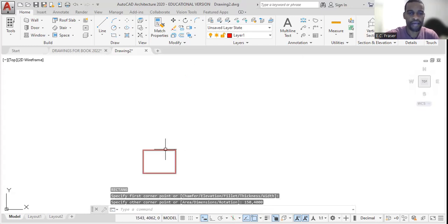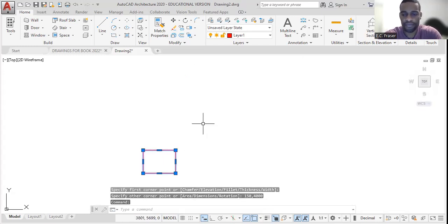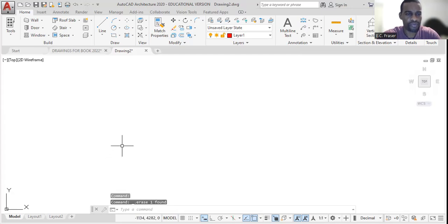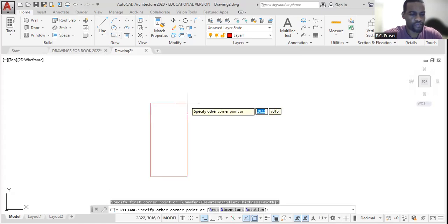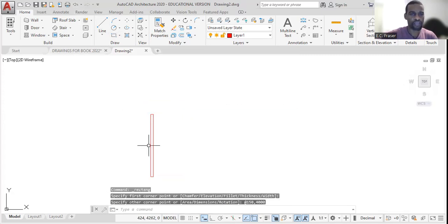Oh, sorry, I need the @ sign here. So rectangle, left click, @ sign, 150, comma, 4,000, enter. So this is my wall, one wall.